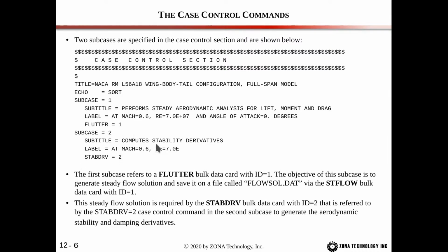So in our flutter subcase, that's going to refer out to the ST flow card, which will save the steady flow onto a file, and then the second subcase will refer to that steady flow to then compute the aerodynamic stability and damping derivatives.